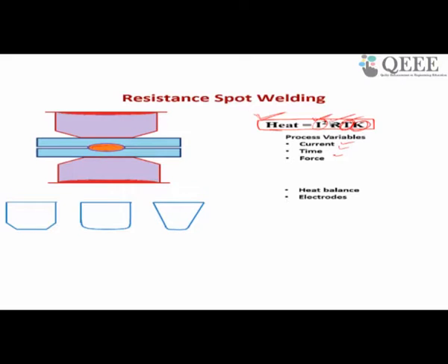The main objective is that in resistance welding, welding happens within a second, a very short time. To reduce the time, but still generate that much heat to weld the material, the current will be very high, in the order of around 15,000 ampere, and the voltage is very low. Now your heat depends upon the current, how much current you give, which is in your control. You have to give current in the order of 15,000 ampere for a very short time.